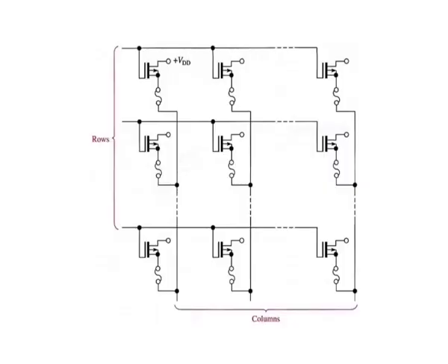The figure here illustrates a MOS PROM array with fusible links. The fusible links are manufactured into the PROM between the source of each cell's transistor and its column line. In the programming process, a sufficient current is injected through the fusible link to burn it open to create a stored 0. The link is left intact for a stored 1.